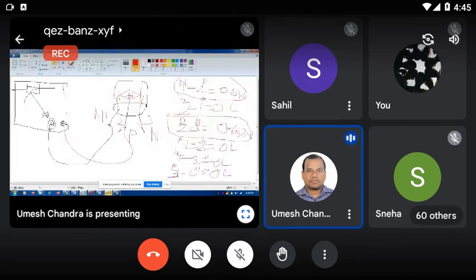Now you identify the NPN and PNP, and after that the emitter, base and collector of a transistor. The pin which is common, that is the base. The middle one is common. Between pins 1 and 2, and 2 and 3, pin number 2 is common, so that is the base.